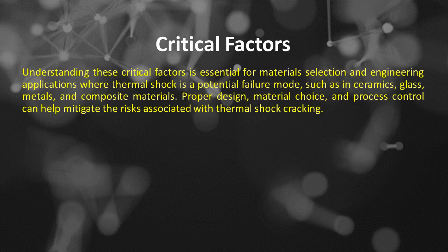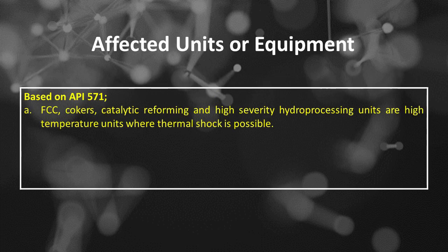Understanding these critical factors is essential for material selection and engineering applications where thermal shock is a potential failure mode, such as in ceramics, glass, metals, and composite materials. Proper design, material choice, and process control can help mitigate the risks associated with thermal shock cracking. Thermal shock cracking affected units or equipment based on API 571, the first is FCC.